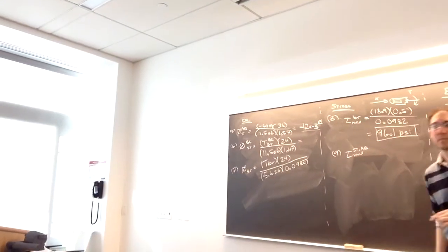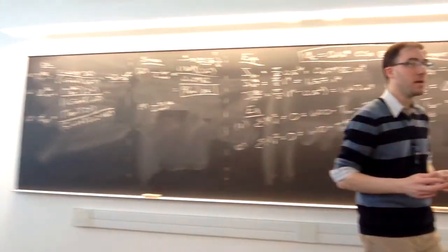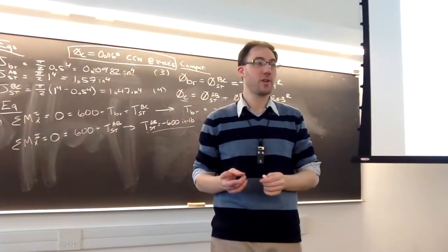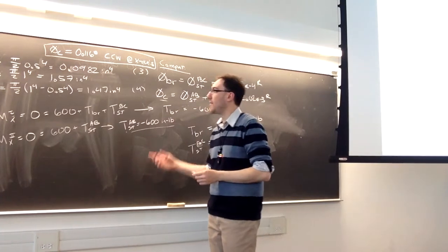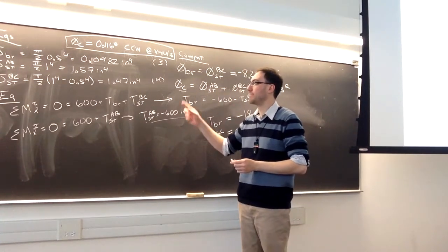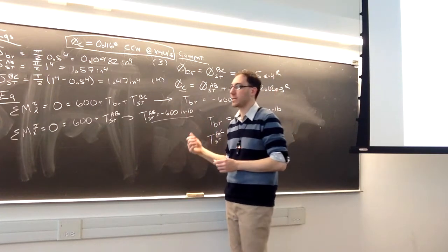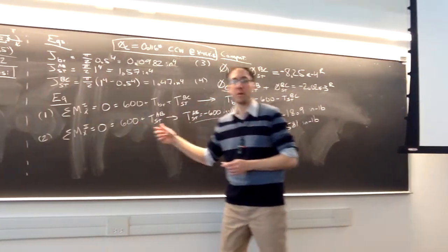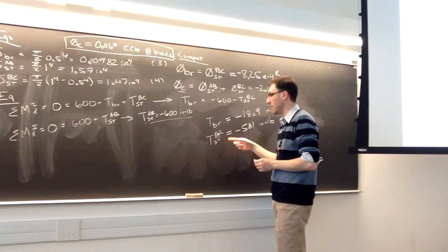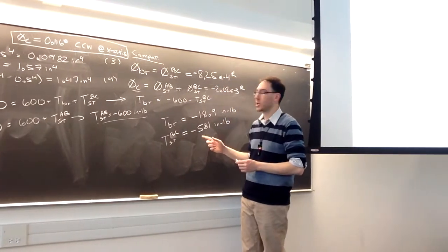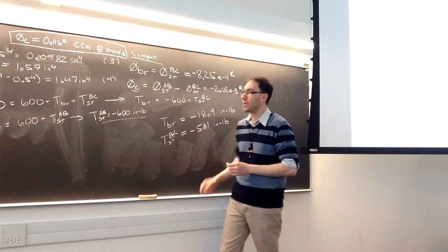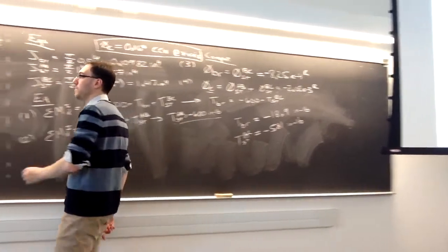However, the steel, we have 2 sections of steel, each one with a different internal torsion, but each one also has a different value for J. They both do have the same outside radius, though. So it's not as simple as just seeing which section of steel has the maximum internal torsion, because we're dividing by a different value. So we do need to check both sections.